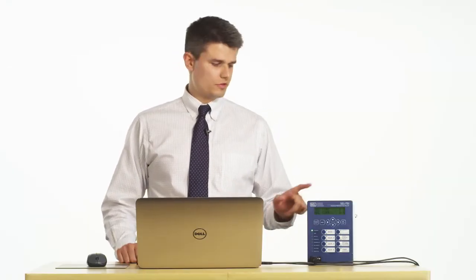Today, I'm going to show you how to retrieve an event from the SEL 751 relay to a laptop. And we're going to learn about the basic functionalities of SynchroWave Event 2015. To gather and analyze an event from the 751 relay, we need to have established the communication channel to the device. Once we have established the communication channel, we're able to gather the event through Accelerator QuickSet.